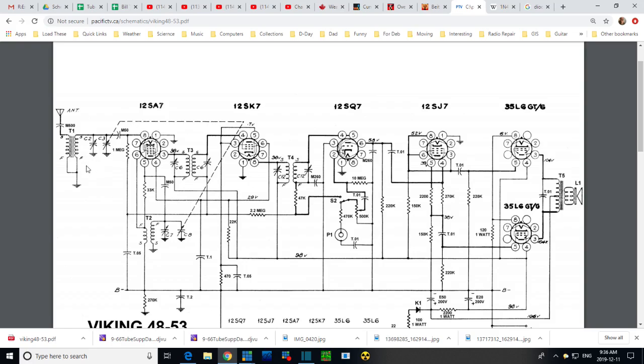If we had another front end out here, another tube and more filtering, more pre-selection going on, then probably this tuning capacitor would have another set of plates, maybe 3 sets of plates. This one only has 2 sets of plates, a set here and a set here. See, they're connected by this dotted line. There'd be another one over here. And then you'd have the challenge of trying to make 3 things track properly all the way across the tuning range. And again, that's a big part of the radio design challenge.